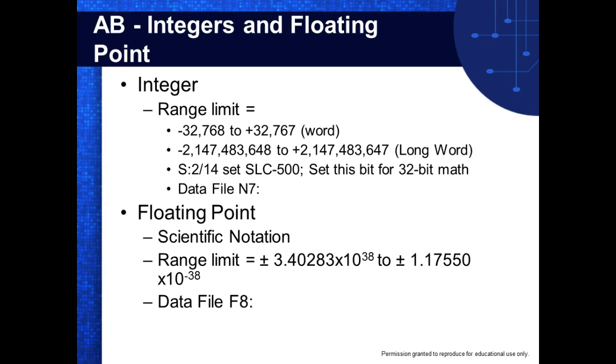Okay, does that make sense? But to use words, you have to get into the PLC status register and set bit 14. We'll show you how to do that. If you set bit 14, then it's going to deal with words.